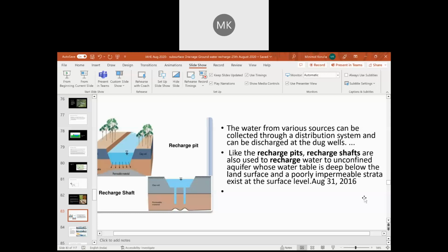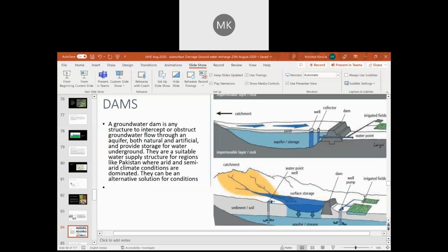So now drainage is very important, especially subsurface drainage, when we are going for ground improvement solutions also. And one of the alternate technologies compared to the normal type of ground improvement like sand drains and all is in fact the PVD. PVD is prefabricated vertical drains. So prefabricated vertical drains are again a combination of a central core and the confinement using the geotextile. So we can call it a special type of drainage geocomposite.